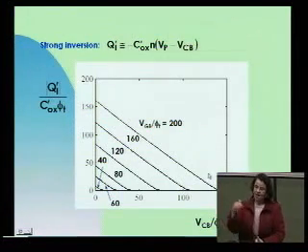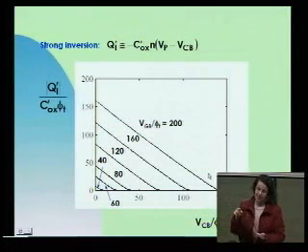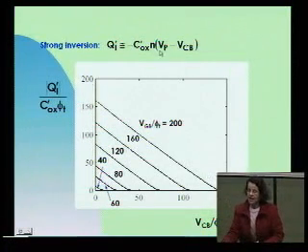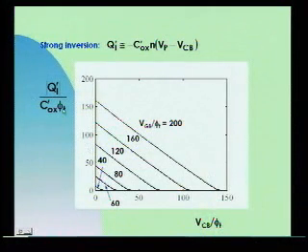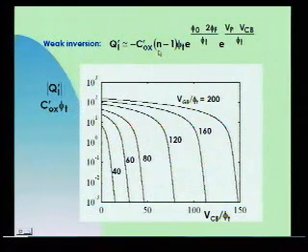Now we will recall, I've shown you this before, that in strong inversion this relationship is a first order polynomial, and the EKV used this approximation. You see that there is the pinch-off voltage here. So the dependence upon gate voltage is inside the pinch-off voltage. And in weak inversion, they use this exponential approximation. This potential here